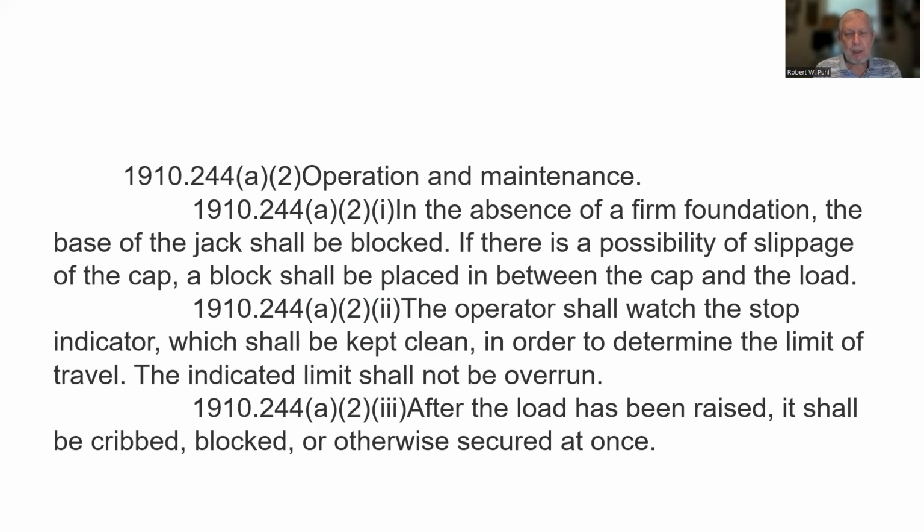So you notice this bottom one here? The jack is used to get the load up, but once it's up, you need to otherwise secure it. You don't use the jack to secure it up while you're working on it. Not a good idea to work under something that's just being supported by a jack.